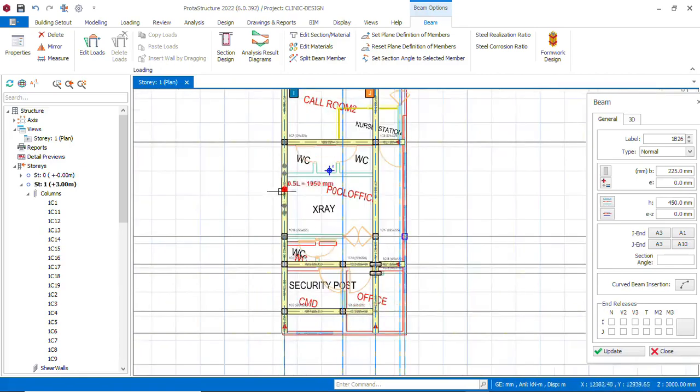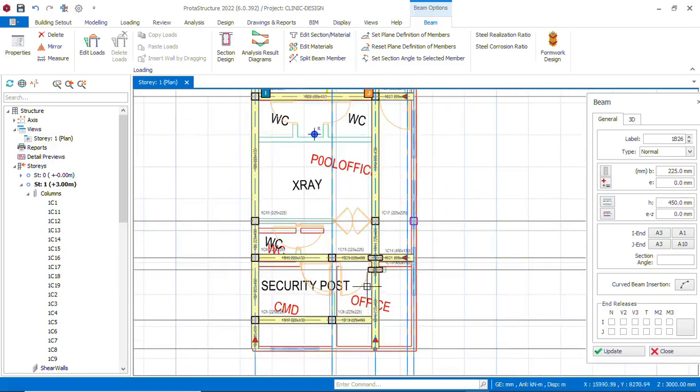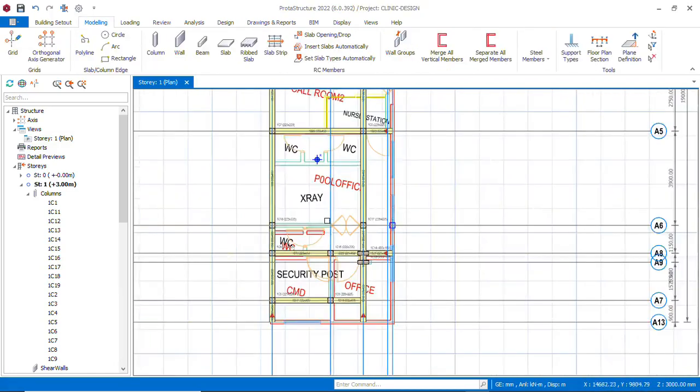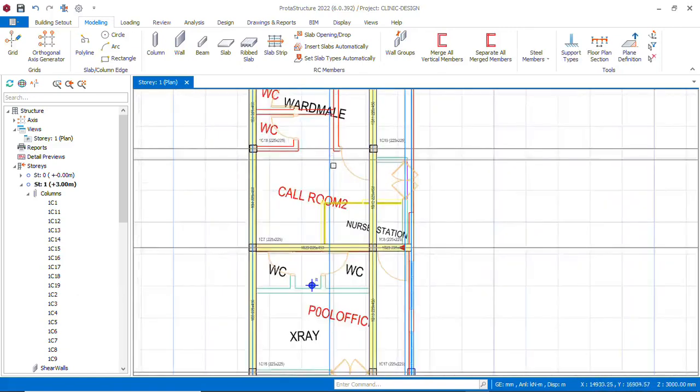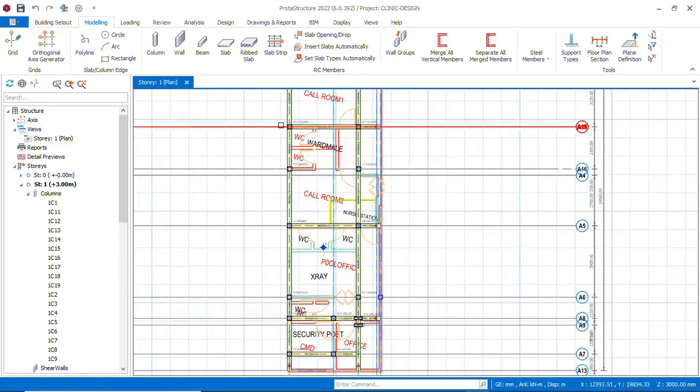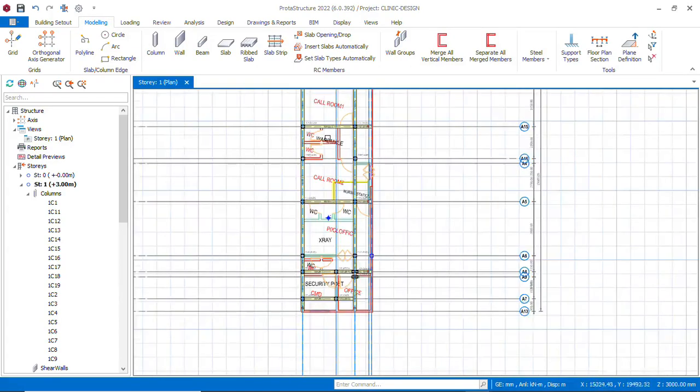So let me check the distance. This panel. Make sure the area of your panel is no more than 30 meters square. Take note of that. Make sure the area of your panel is not more than 30 meters. So we check this panel and we'll see if it's too big, we can split it. If it's not too big, we can read this as a panel.